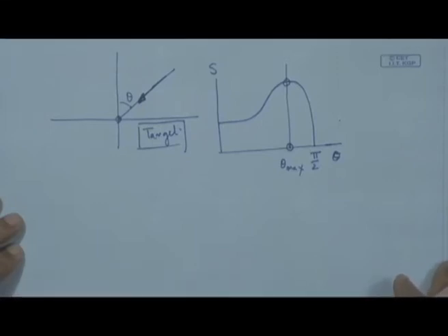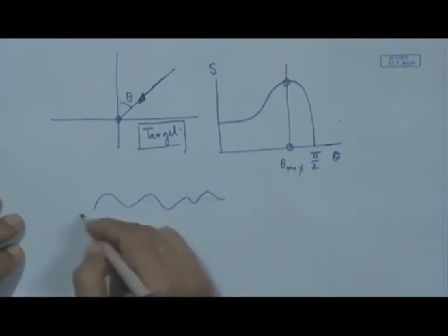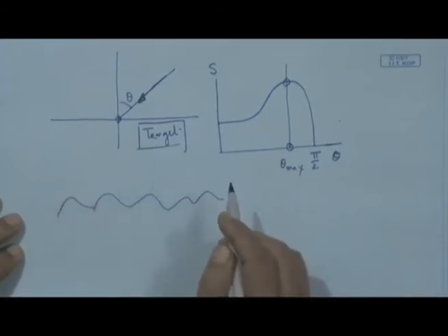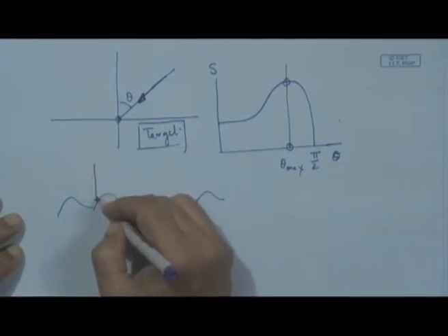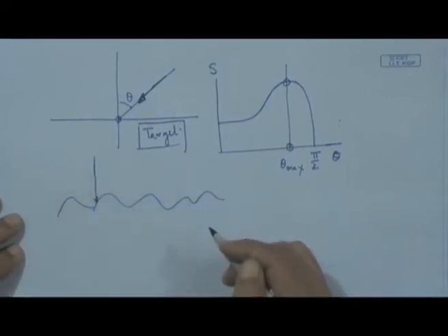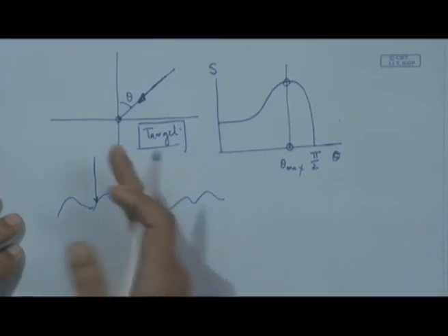We have unevenness on this target surface. So, even if we have a normal incidence of the argon ion on the target, depending upon the undulation on this surface, if we consider this is striking at this point, it is normal with respect to the axis of the target. However, with respect to this surface this is not actually straightforward.